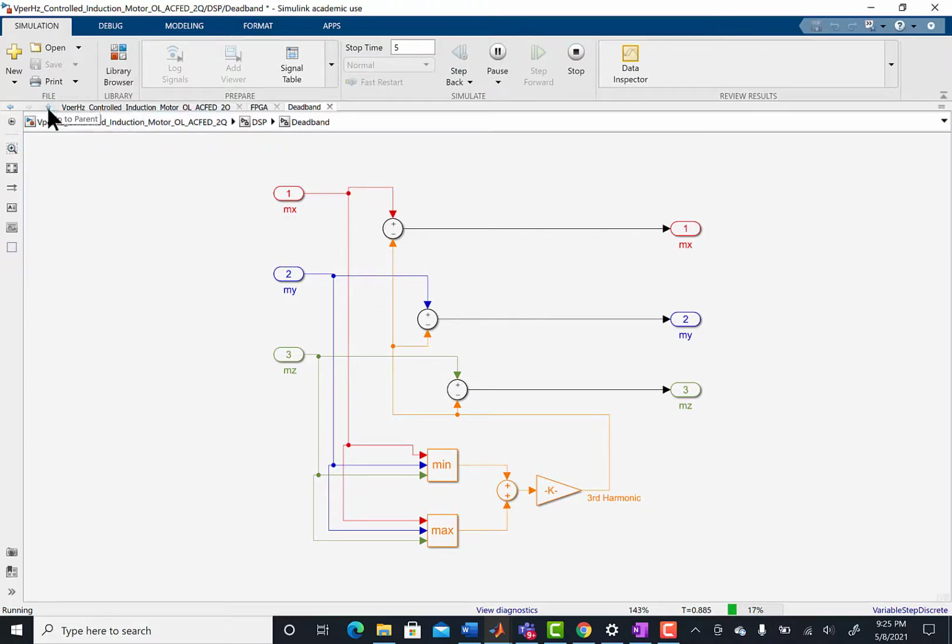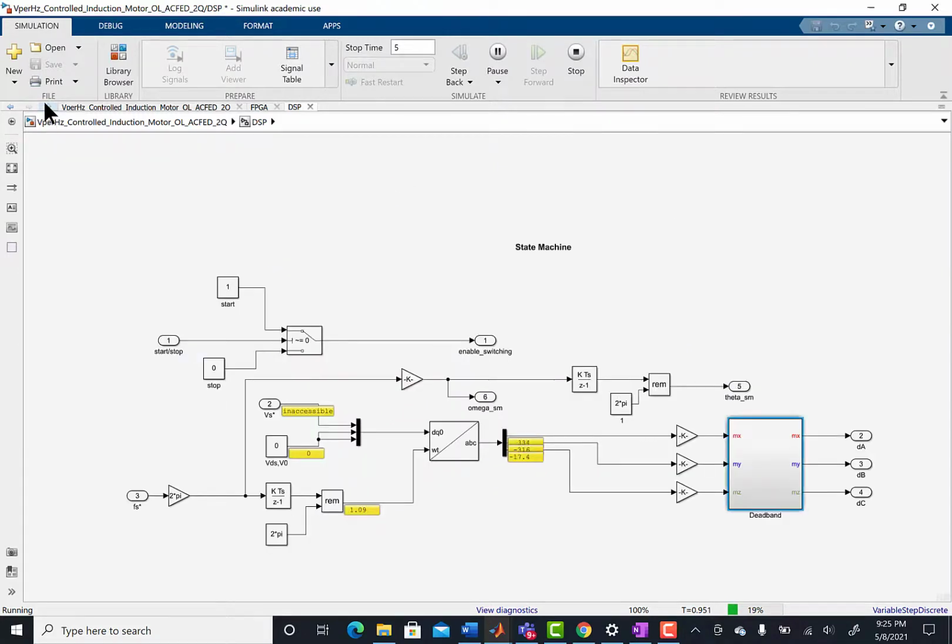This is something that Graham Holmes pointed out. He and Tom Lipo had written this famous book about pulse width modulation. But in an early paper in the 90s, he pointed out how you could simplistically create the same thing that's quite complex in space vector modulation, as long as you have analog controls, that would be exactly as good as space vector control.